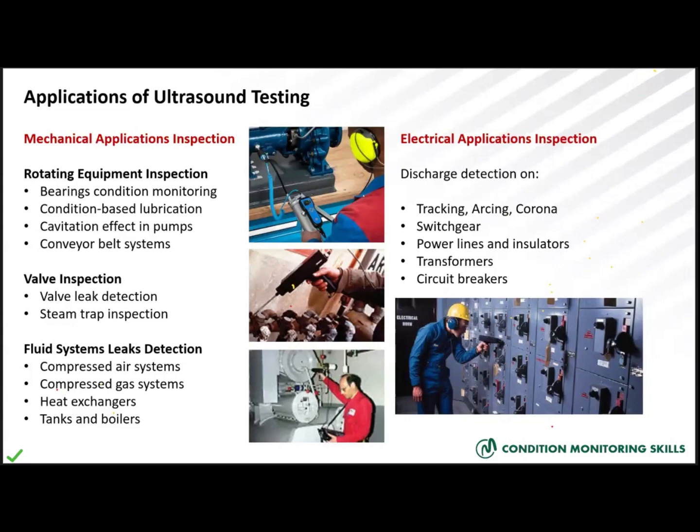Ultrasonic detectors in general can be used to identify problems related to component wear as well as fluid leaks, vacuum leaks, steam trap failures, and so on. A compressed gas or fluid forced through or leaking through a small opening creates turbulence with a very strong ultrasound that could be detected using the ultrasound probes. Even though such a leak may not be audible to the human ear, the ultrasound probe still detects such sounds.